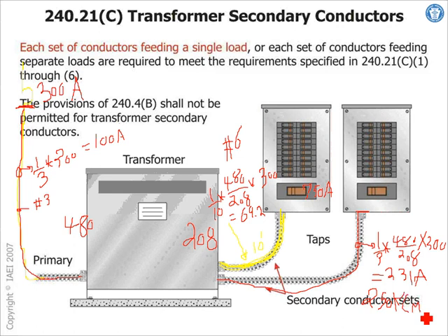And that 25 feet has to be in an industrial installation, so qualified people like yourself will only maintain these systems. So that's manufacturing. If you have manufacturing, they allow you to tap from a secondary of a transformer and go 25 feet before you put your circuit breaker. Those rules are only for manufacturing.